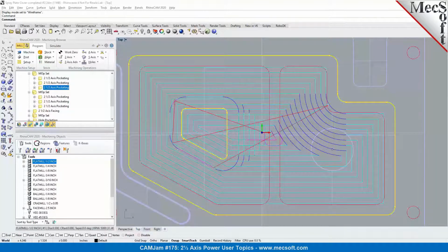But in other cases, let's say you're machining a NURBS curve and we fit an arc to the resulting toolpath, that might result in a little bit of an error. So you have to be careful about what we call tolerance stacking, because you have a machining tolerance and, on top of that, the arc fitting tolerance. I hope that makes sense.